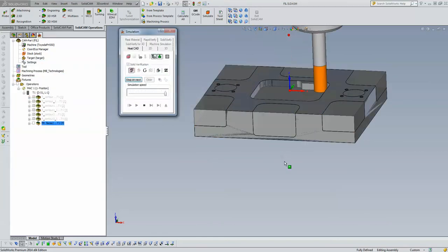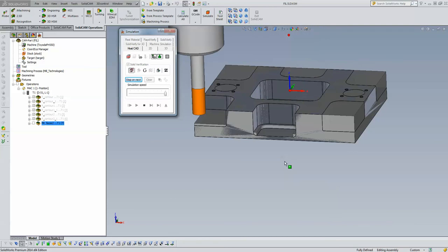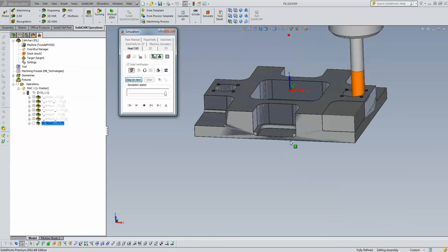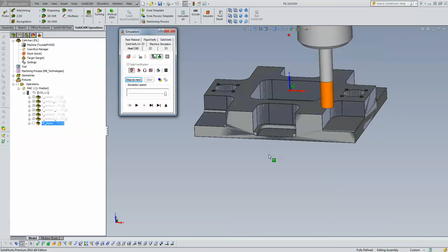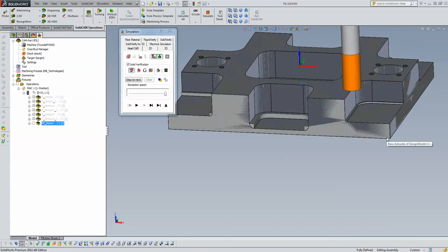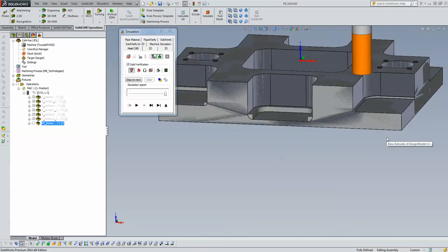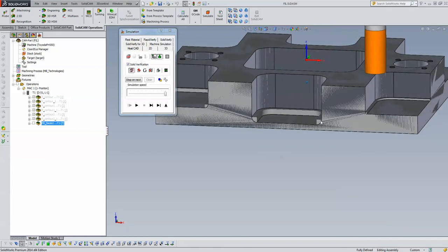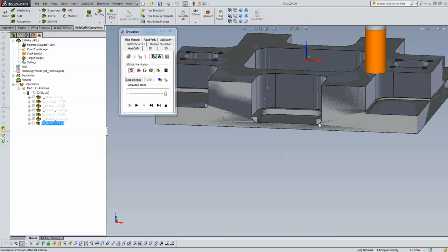Running our simulation, you'll see it'll do every single pocket automatically. And it automatically also recognizes the diameters that I have over there without me having to do separate operations for each one of them. It recognizes that automatically in each one. But you know what? Remember, I did say that I want to have these large radiuses over here with more step downs, with more steps on it instead of the typical one step as I did over there.